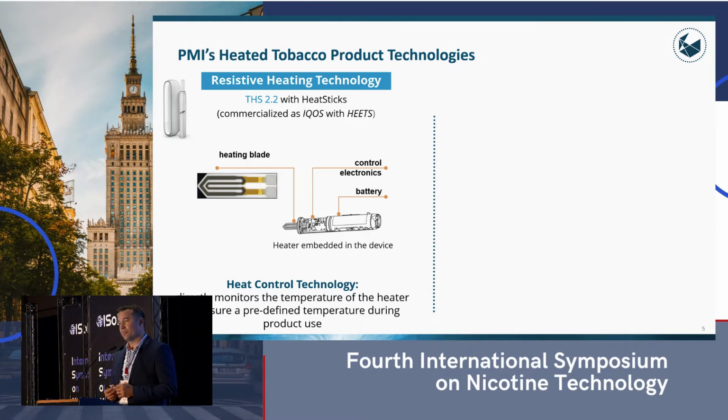Now the beautiful thing with the platinum track is that it acts as a temperature sensor at the same time as it produces the heat, which means you can control the temperature directly with this technology. And this is, of course, fundamental to be able to ensure that we do not get combustion, because you really need to control the temperature to not get an uncontrolled situation.